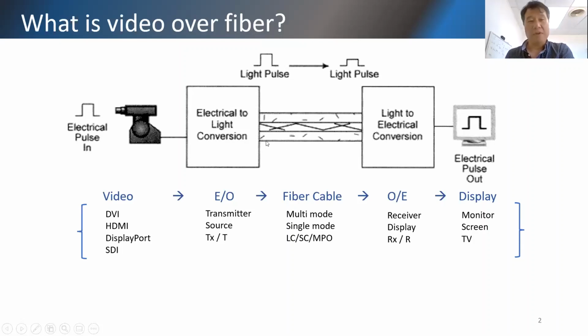And of course, you have optical fiber cable. You're going to hear the terms multimode fiber and single mode fiber. There are also different types of connectors that different players may use, such as the LC connector and the SC connector. There's also something new that we think is very useful, called the MPO connector. These are probably the most common connectors you're going to run into in video over fiber applications.